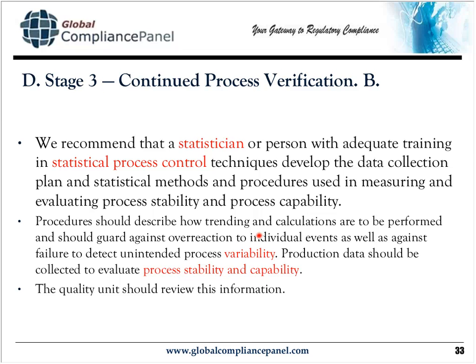And it depends upon how many lots you're making. If you're making 4 lots a day, let's face it, once a week is not enough. And it might need to be every 2 days or even daily. Now, you're looking at process stability and capability from your production data. So again, you should still be calculating your capability indices. But if your SPC charts are stable, you probably don't need to look at capability indices.